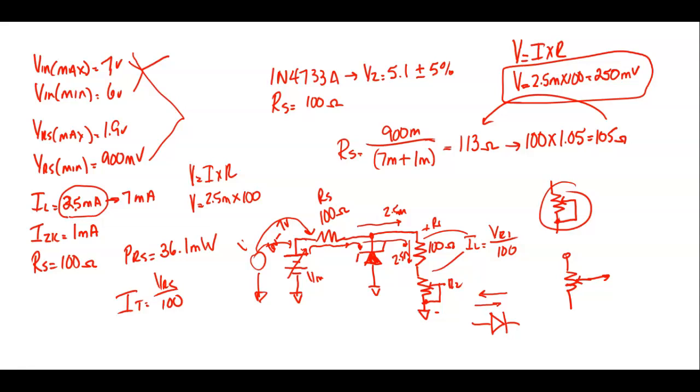right? So what am I supposed to have on my input voltage, guys? Does it say? I cannot regulate at 5.1 volts with a minimum input voltage of 5 volts. Your input voltage is unregulated.